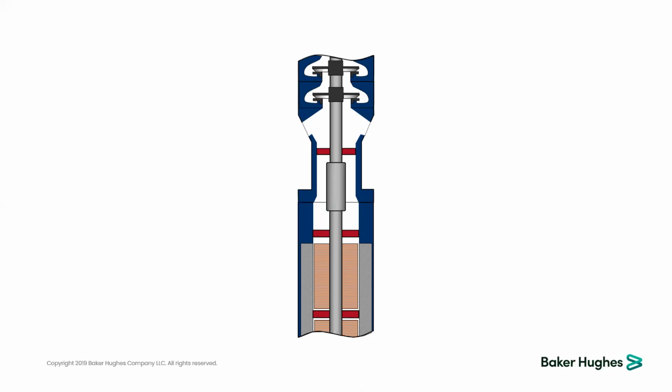If we could just couple them together, the shaft torque would go directly from the motor shaft to the pump shaft. And this spot of connection would have a higher torque, so it would be a higher risk point.